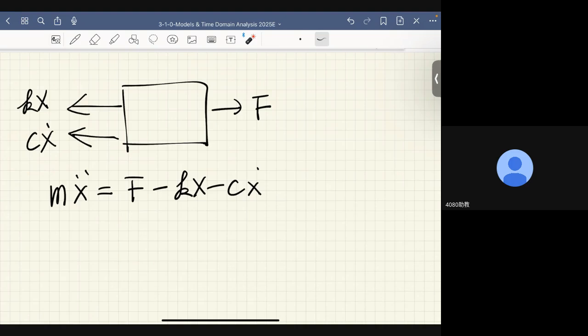So the impact of damping force really depends on how large the spring force is. If you have a very stiff system, with a very large spring constant, the spring force will overwhelm and suppress the damping force, and it will look very, very small.